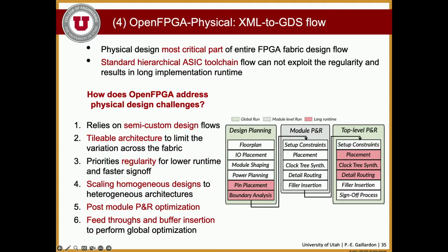We had to introduce several innovations on the physical design of these chips because we want to use standard chip design techniques, and FPGAs are pretty unique compared to regular chips. They do have a large number of individual instances, so that hits the scalability of the placement and routing algorithms.